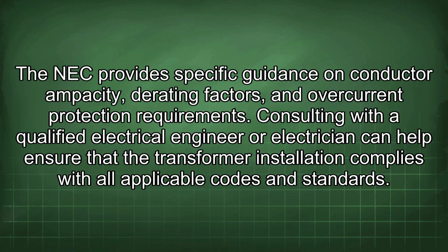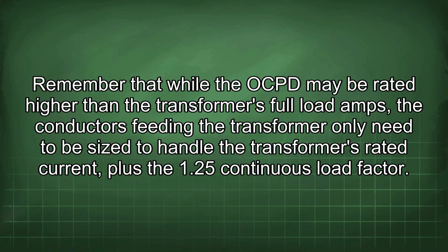The NEC provides specific guidance on conductor ampacity, derating factors, and overcurrent protection requirements. Consulting with a qualified electrical engineer or electrician can help ensure that the transformer installation complies with all applicable codes and standards. Remember that while the OCPD may be rated higher than the transformer's full load amps, the conductors feeding the transformer only need to be sized to handle the transformer's rated current plus the 1.25 continuous load factor.